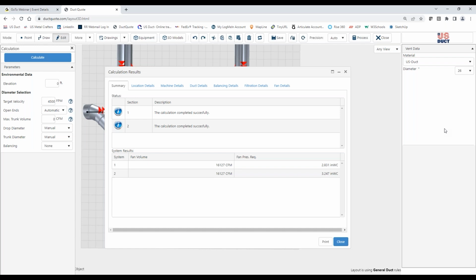And don't ever, if you can avoid it, mismatch the size on double branches like what you saw there, which was a 24, 18, 16, 4. Move that small 4 into its own single branch, okay? And then finally, use tapered trunks. What you save in power and cleaning out and maintenance of the system is probably going to more than pay for the duct if you've got duct to reuse.